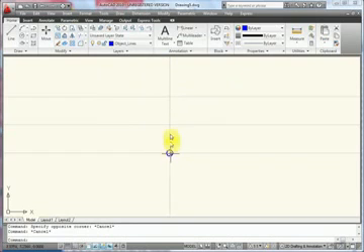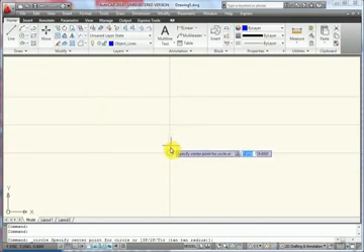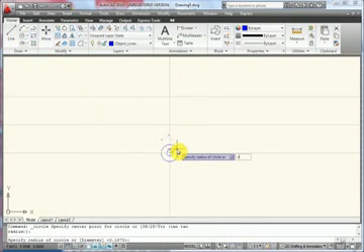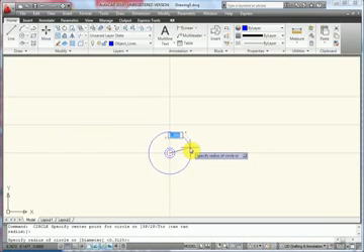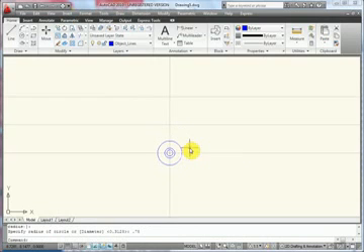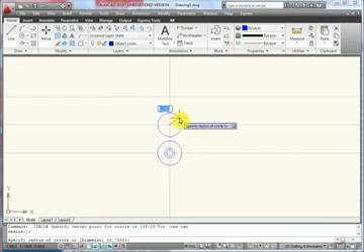Now I'm going to draw the rest of the circles that are either concentric or based off these other intersection points, all of which will be center radius circles. So I have one more that's a diameter of 5/8, and if I want to, I could actually input this as 5/8. That represents the counter bore for the bolt hole. And I have one more circle out here that's actually a radius of 3/4, so I don't have to change the input mode. And I'm just using the spacebar to re-input the command.